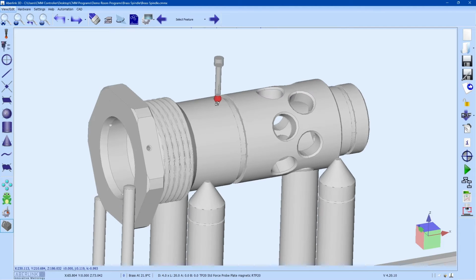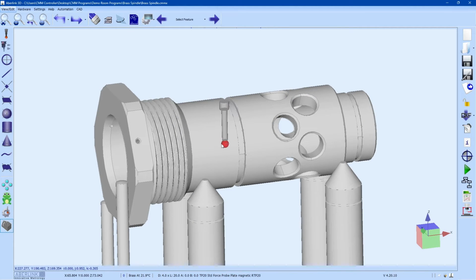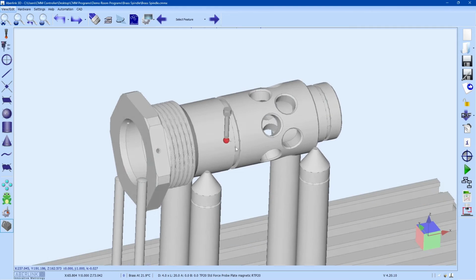So we're measuring this as a cylinder. It has its own axis, it has its own alignment, and the circle that we use for the datum and subsequent concentricity callouts is going to be true to itself. There's no skewing or projection issues. Okay, so let's have a look at that with a program.